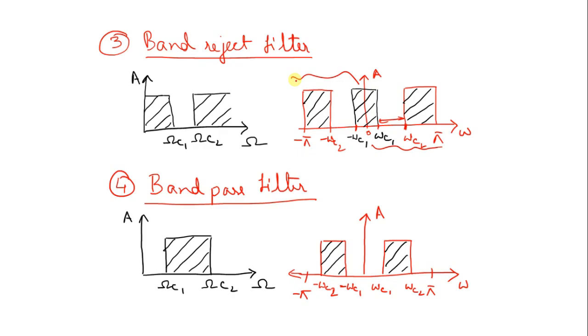Okay. So whenever you get something like this, you draw the frequency response in the positive frequency range, that means 0 to pi radians, and then you mirror it in the negative frequency region. Okay. So similarly, if you make the band pass filter, in the positive region it should be like this. So in the negative region, you will be having something like this. Okay.